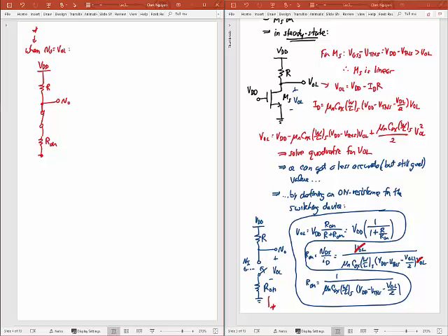And this is a problem. Okay, this is a problem for me right now because I have current flowing. Right, I have this VDD across two resistors. Yeah, it's dragging this V out equal to VOL. It's pushing that to a small voltage, which is what I need it to do. Right, I have a high voltage at the input. I have a small voltage at the output, but I have current flowing. And so if I have current flowing, that means I'm consuming power. So that current is going to be VDD divided by R plus R on.